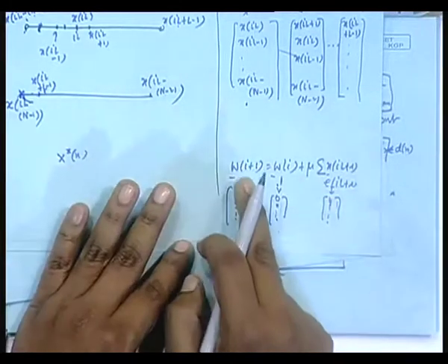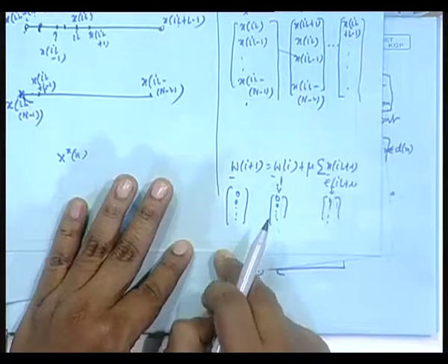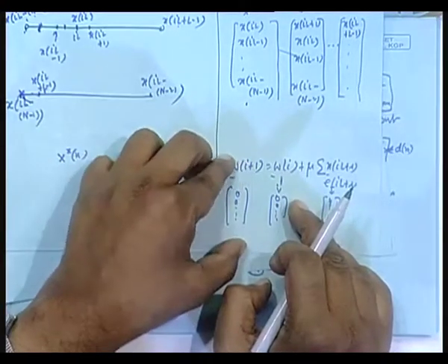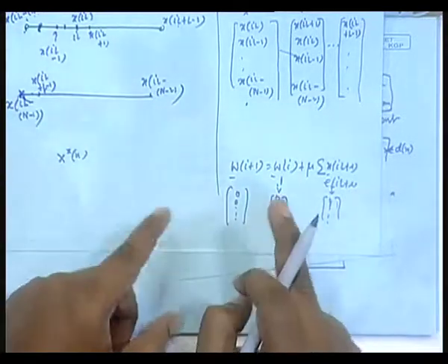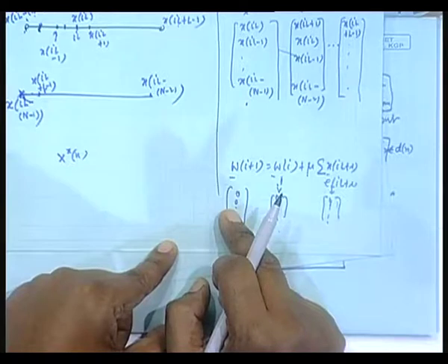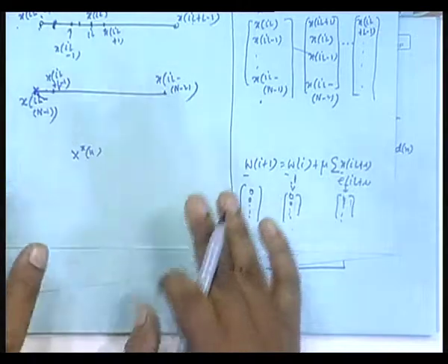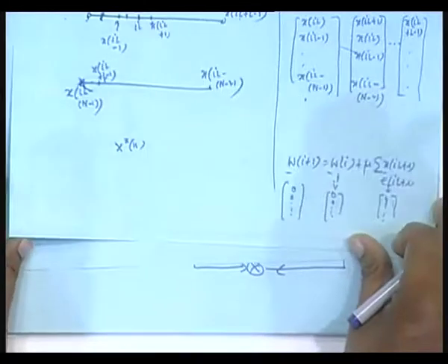If you add them, naturally here also the last L minus 1 positions will be 0. That suits me, because if I take the DFT of that, it can be used in the filtering part in the circular convolution, because there it was needed that the last L minus 1 entries should be 0. Okay, see how beautiful this thing is, things are fitting in all directions.